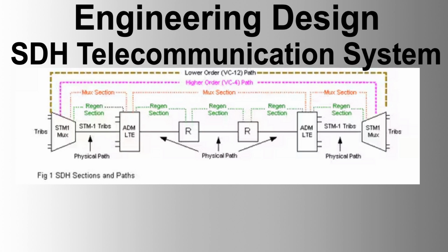Network management systems. General requirements. Integrated NMS. An integrated network management system, NMS, for monitoring the operational status of the transmission systems and miscellaneous equipment shall be provided. System monitoring. Dedicated network management systems are required for the SDH network and all interfacing services, and a fiber cable monitoring system, FCMS. The installed NMS at all locations shall maintain real-time status of the fiber optic network and all connected network elements.